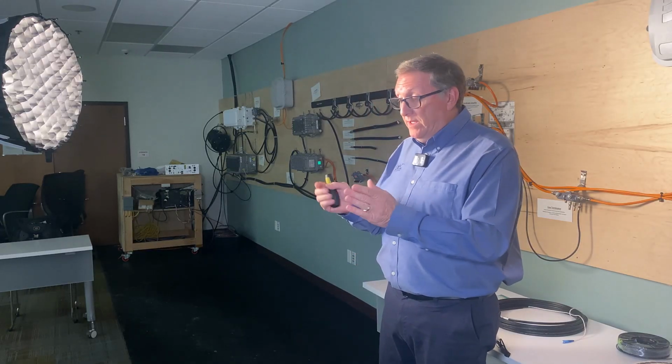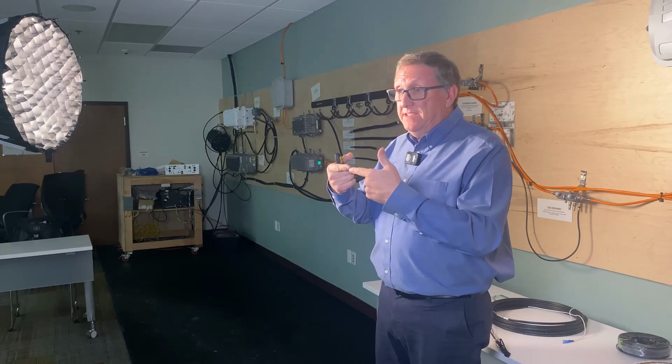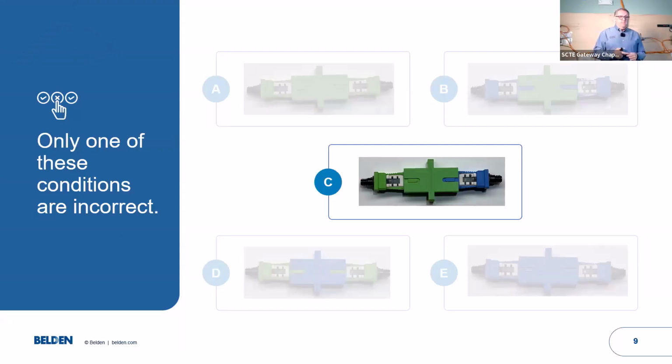There could be possibilities of spacings in between. The spacings in between are actually really, really close. Tight tolerances. Very tight tolerances. But one of the bigger issues that we have goes back to dirt again. When you go to connect two pieces of fiber together, you can actually transfer dirt from one to the other, right? And depending on how hard you push, you can cause things. But technically, I've never seen a bad bulkhead. I've seen connectors where dirt from one gets into another. Yeah. I've seen light that was bad. We'll talk about that, burning connectors out. But I've never technically seen a bad bulkhead.